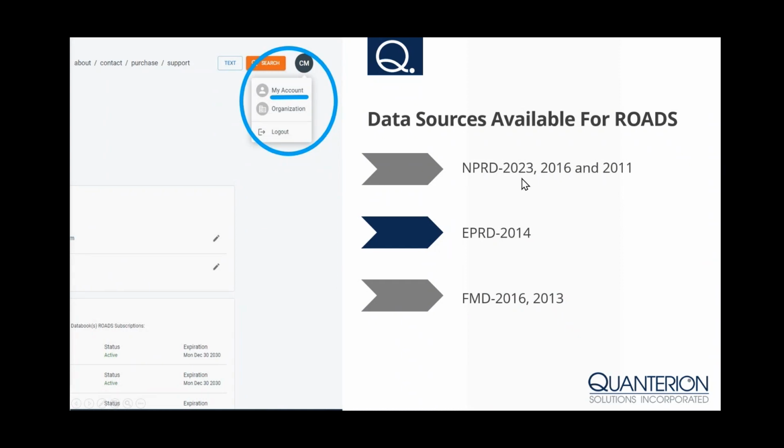The only reason you might want to exclude the newest version would be if you've already done a reliability prediction or a data source lookup and it was based on 2016 or 2011, and you've done this for numerous items and you want to be consistent with how you source your surrogate data so that you can perform relative comparisons from one system to another, which, given the statistical nature of reliability prediction, is a non-trivial concern. Sometimes you want to go back to the old data just so that you're consistent.